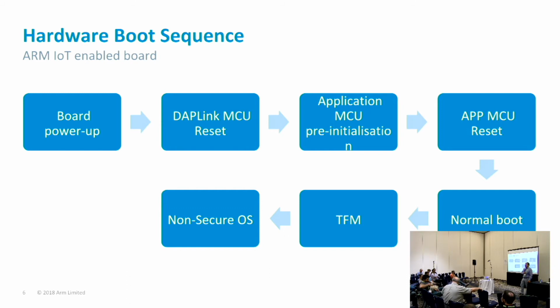Some of these production devices that I have worked on in the past will have some sort of production switch as well. So you have the device in the development phase, and by flipping that OTP, you say that from this point onwards, it's all security protected. You can't do rollback. Basically, you have a limited number of bits in OTP, so you can only fuse so many times. And if you put your device in the CI, after, I don't know, 256 operations, you need a new board.